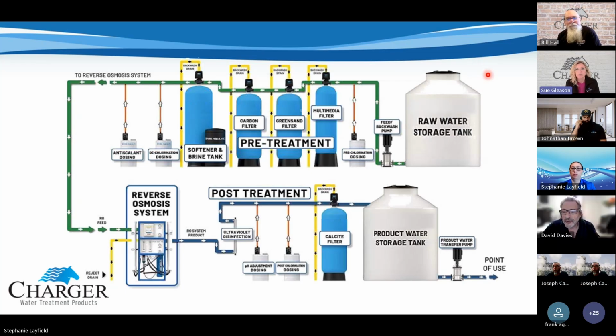David's going to have to answer that. Yep. I think he meant the raw water. The raw water? Yeah, if you could put it into the storage tank right off the bat, you've got plenty of contact time there, and you're not sitting there with stagnant water of unknown quality. So yeah, that would be an excellent time to introduce the chlorine to the system.